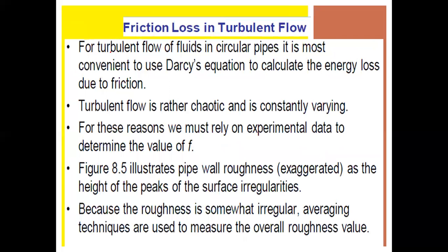For the friction losses in the turbulent flow of fluids in circular pipes, the most convenient way is to use Darcy's equation to calculate the energy loss due to friction. So in the turbulent flow, we use the Darcy-Weisbach equation to solve the energy loss for circular pipes only.